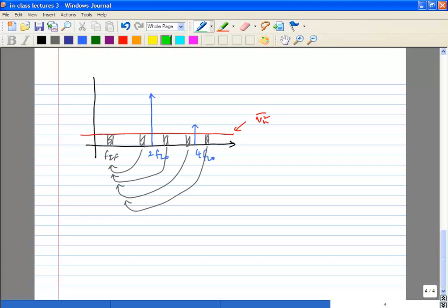If you look at the pulse train which is sampling your noise, with this TS, what does it look like in the frequency domain? It looks like a sinc function, right? That's at 1 over TS. So what happens when you increase the width? Obviously there is only a limited amount of noise, it's not an unlimited amount of noise which adds in.